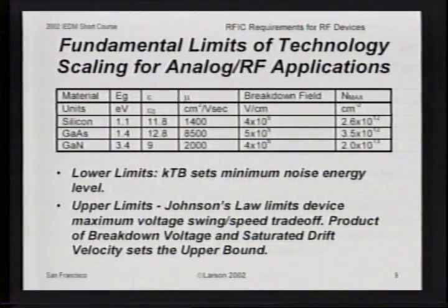Silicon is, of course, the most common technology of all, and we'll spend most of our time on that today. But gallium arsenide also has some very fundamental advantages compared to silicon, and gallium arsenide retains a strong niche within the power amplifier field for reasons that I'll talk about a little bit later. From a technology perspective, the key issues are the electron mobility, breakdown voltage or breakdown field, and then the maximum charge density that you can get in a given conducting channel.